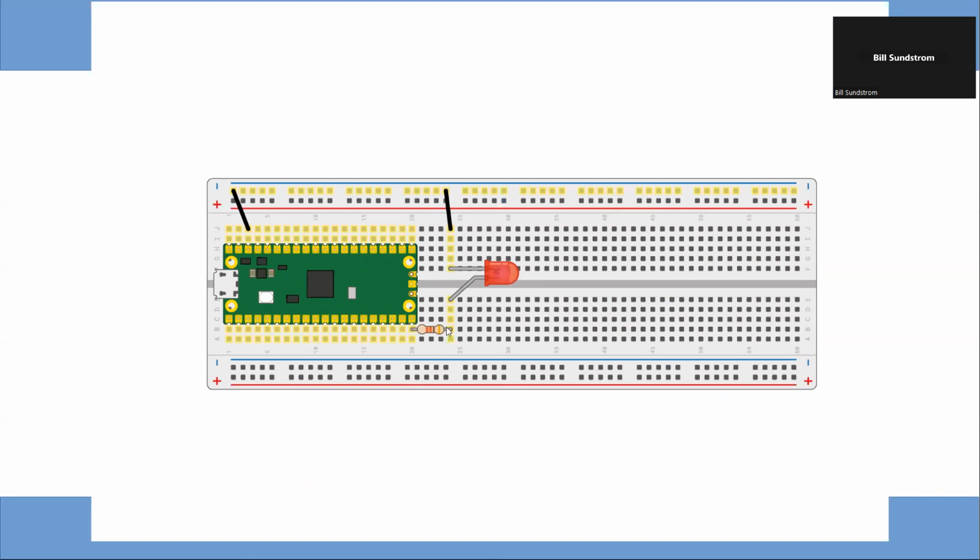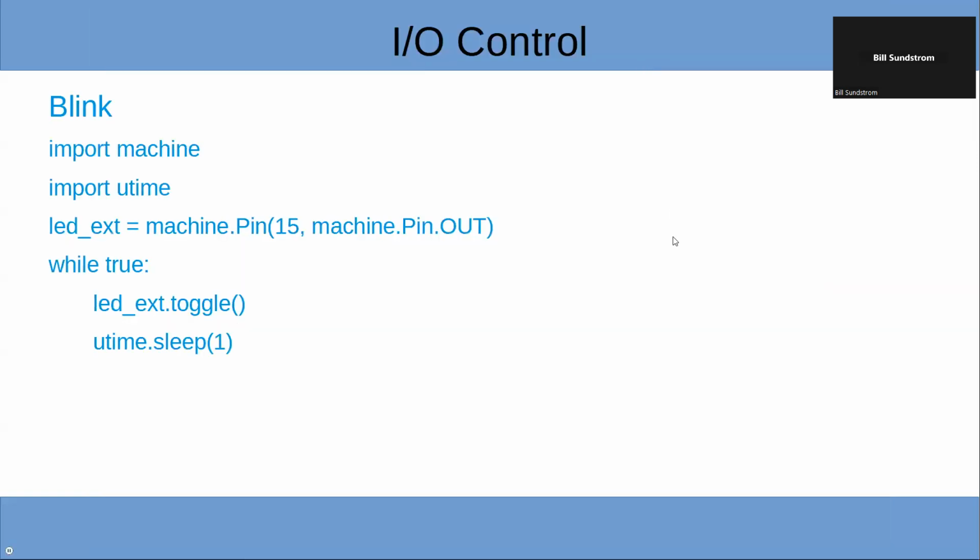So it's just a resistor in series with the LED back to this pin over here, which is probably 5 volts. Or it could be ground, I don't know which way it's going, and I can't tell. That's supposed to be pin 15 where it's shown.